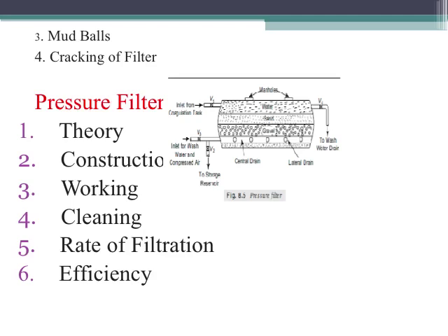The high velocities created around the edge of these balls will displace the gravel, thereby forming mounds, while above the balls the sand is improperly washed and mud accumulates. This means that once mud ball formation starts, they go on increasing in number and density until the entire space in the filter box gets filled up with them.